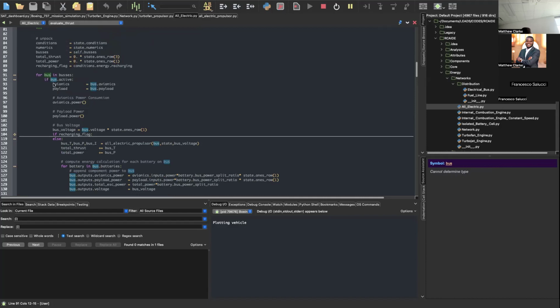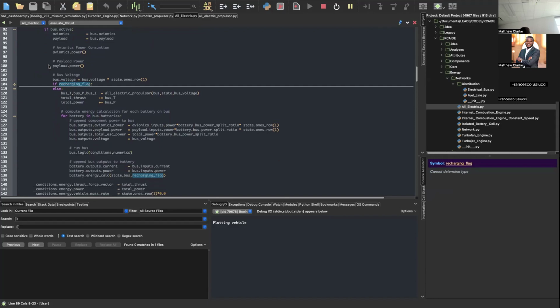So for the lift plus cruise aircraft that some of you have been doing battery noise modeling and battery modeling on, the lift bus has 8 rotors and 1 battery, and the forward bus has 2 rotors and 1 battery. It still accumulates all of the thrust and all of the power, but it splits the power on the batteries that are connected to that actual bus itself.